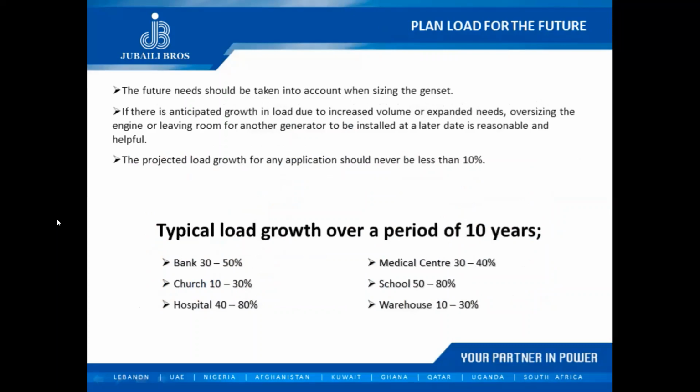So typically speaking, whenever we're sizing a generator, we also have to account for future expansion. Now this slide is not very important, but minimum you should consider 10% future expansion, okay? And below here, you'll see load growth over a period of 10 years. Now, this is typical. This is not a rule. It's just a rule of thumb, okay? For different applications like medical centers or hospitals or whatnot, you'll see different load growth over a period of 10 years, which is equivalent to the numbers you see here.